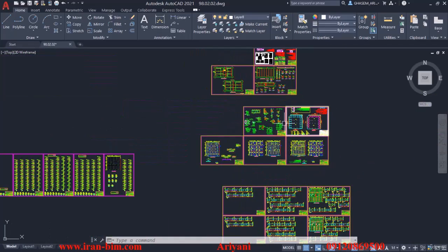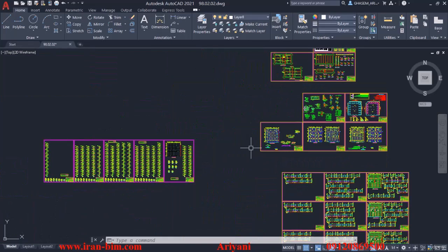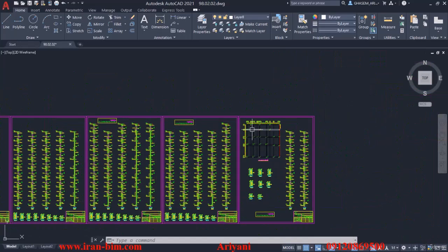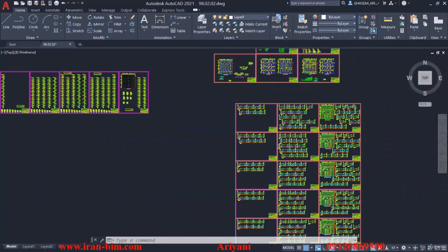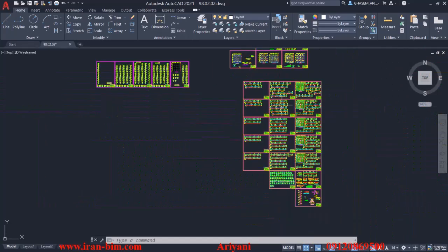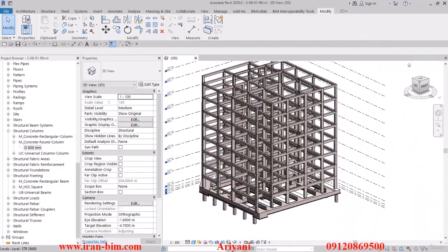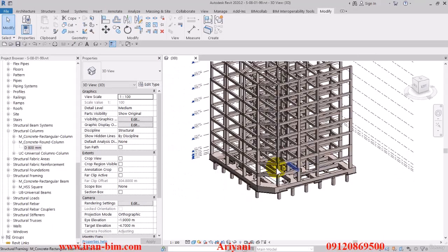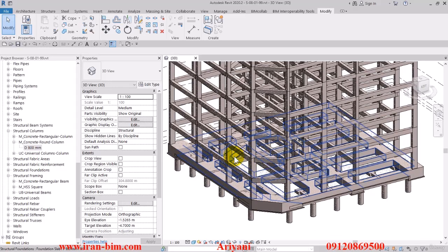And that's why we chose a residential design, because you can find about everything in it and you'd have to deal with all of those things. And if you take a look at the file, for about every axis or every column, we have one specific type that needs to be used. And the same goes for the beams. So if you try to work a project like this, you can really get good at designing and just get to grips with it. So now I'll complete the beams and the unilith, and then after that we can get to the rebars and the reinforcements.